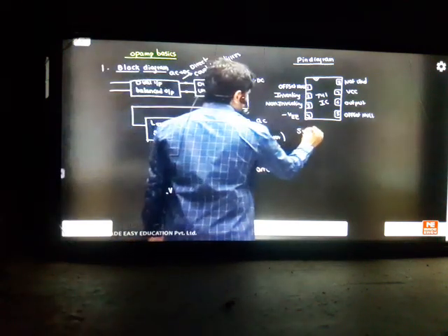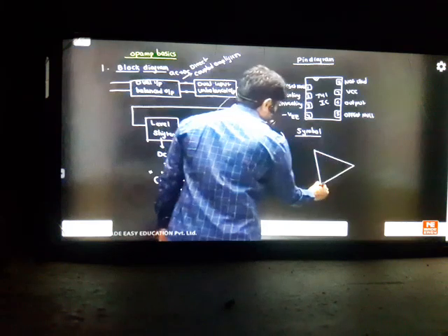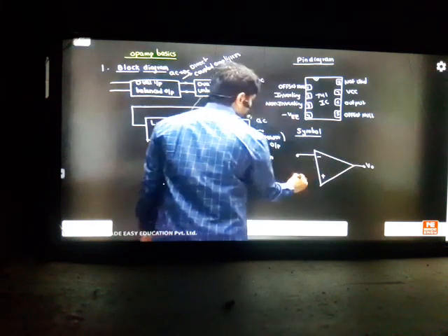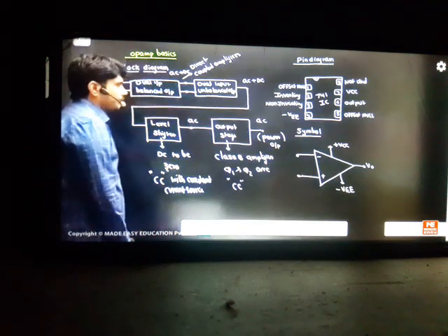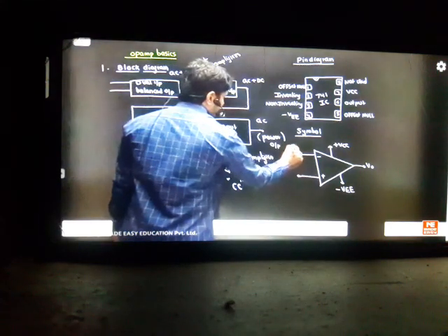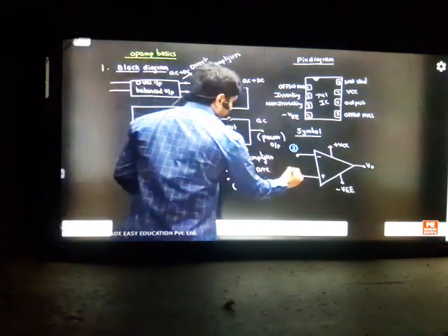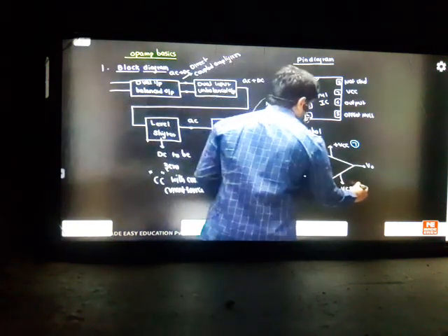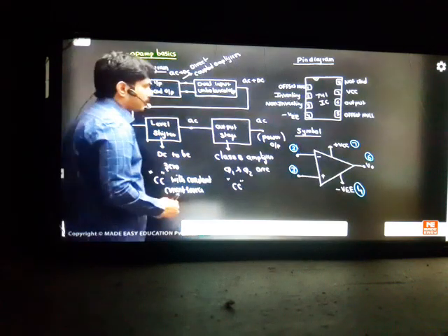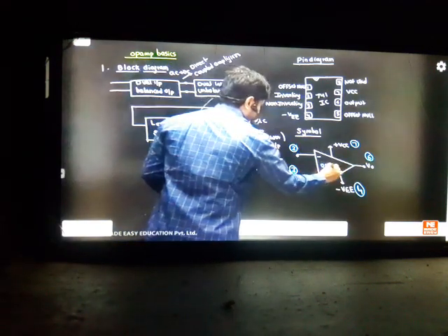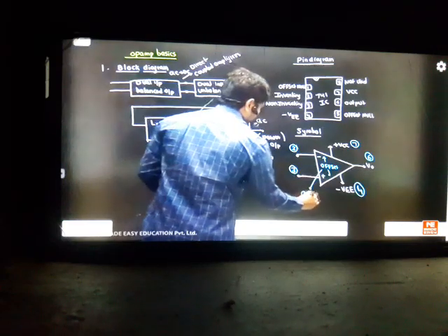Next we have the symbol. Generally, how the symbol looks, most of the time we see op-amps as an arrow-like symbol with minus and plus, we see the output here, and we have 2 inputs. We have some batteries here, plus VCC, and one more battery, minus VE. So this is called the symbol representation of your op-amp. According to these pins, you can see what pins I have used in the class. This is the second pin, called the inverting pin, pin number 2. And the plus pin here is pin number 3, called the non-inverting pin. VCC is here, the 7th pin I'm using, and minus VE is the 4th pin. These are the pins I have used. And the 6th pin we are using for output. So the 1st and 5th pins are the offset nulls. This is the offset we have inside. Unwanted things will be there inside, and to nullify this, we have pins 1 and 5.